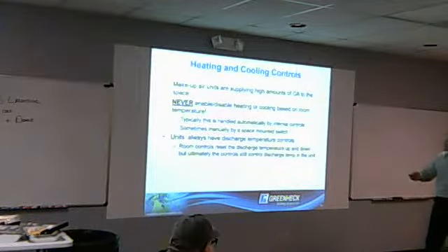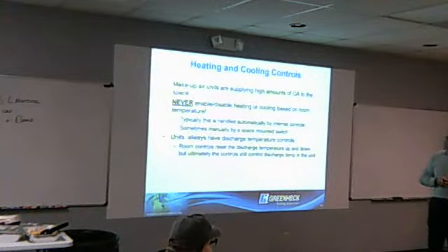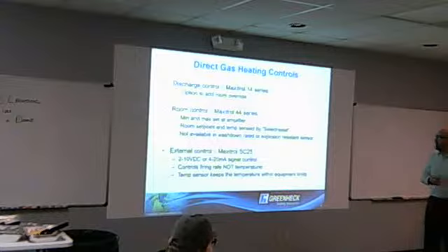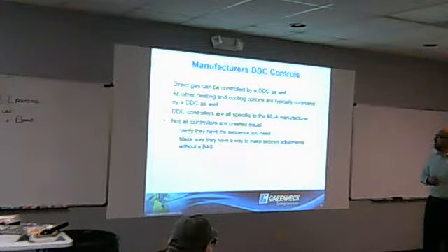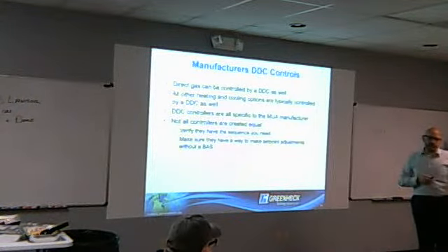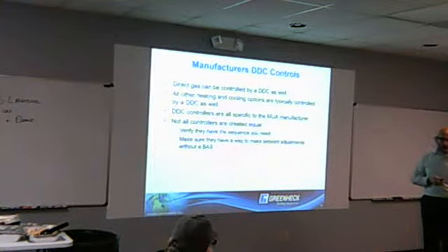Discharge control, because we want to maintain that neutral condition. So if it's 60 degrees, 65, 70, whatever it may be, you want that burner, indirect or direct firing, to create that leaving air temperature. We talked about Maxtrol and the option to override; there's a different series, 14 or 44, depending on how it's configured, or external control. DDC controls, we talked about those. Sometimes they're unique to manufacturers, but if somebody has a really good controller, we find multiple people will buy that controller just because it's good, it's durable, and it gives them ease of interfacing.